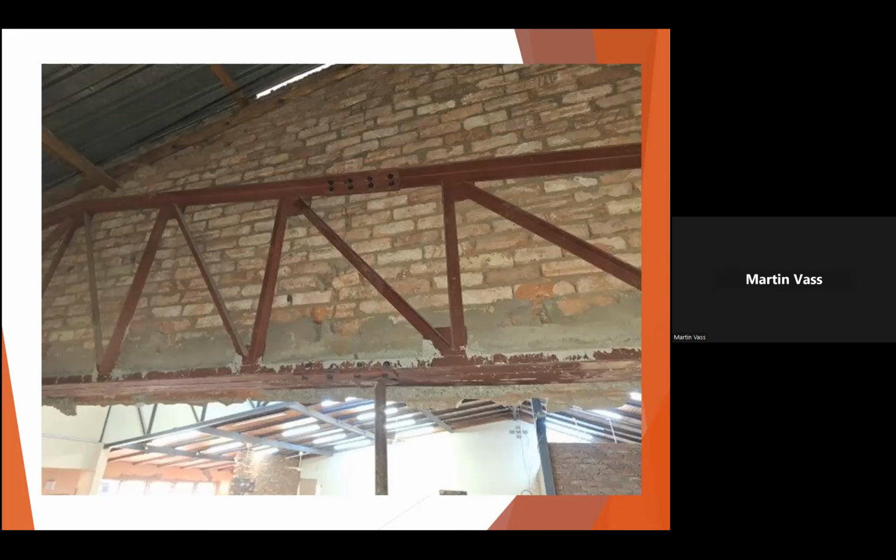The problem is there was no load on that truss before they demolished the brickwork. You can't get load on that truss until that brickwork fails. Unless you jack that truss up, there is no way you can get load onto it. And that's exactly what happened.